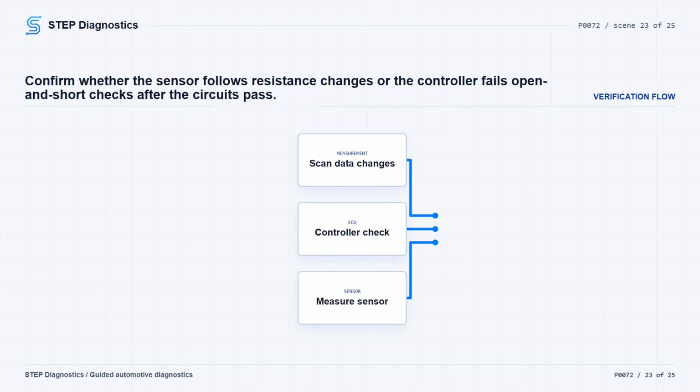If the actual temperature can be acquired or reasonably estimated, measure resistance across the temperature sensor terminals and compare it to the table. If a table is not available for the sensor being tested, connect the electrical test kit leads to the harness connector, flip the switch to adjust, turn the ignition on, and slowly adjust resistance while watching scan data. If the temperature or voltage value changes as resistance is varied, that indicates the temperature sensor is likely faulty.